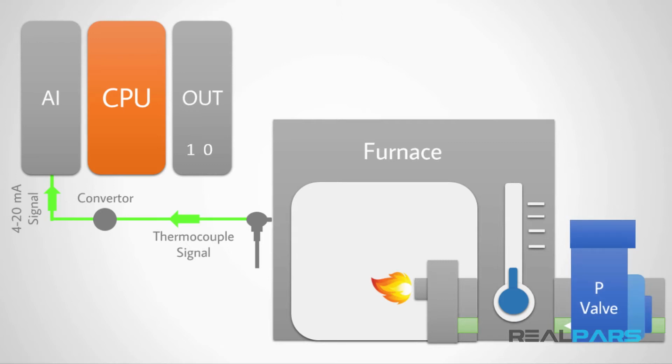The way this valve works is it gets in the way of the incoming gas to the burner, and in this case, the amount the valve opens up will control the amount of the incoming gas to the burner. The more open the valve, the more gas passes through and gets to the burner, and therefore the more heat the burner can generate by burning the gas, and the more the valve is closed, the less gas passes through, and hence the burner generates less heat.